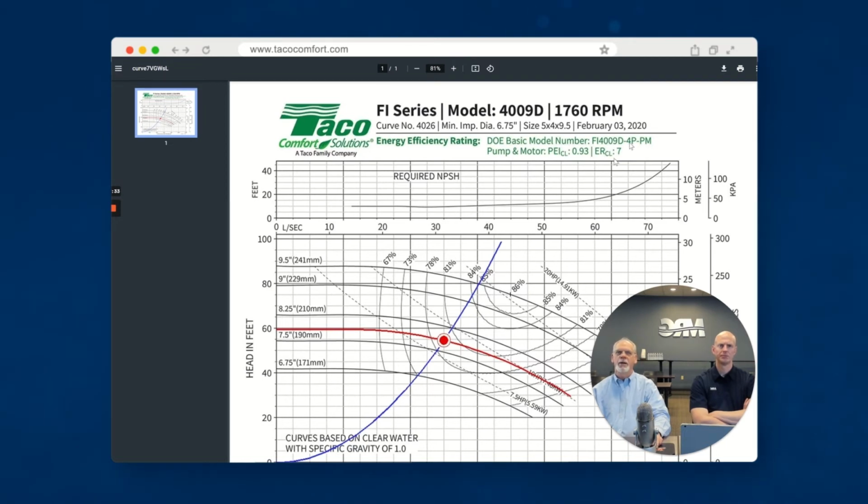This pump here does have a 5-inch suction. We can change again with a 6-inch by 5-inch suction diffuser to adapt to our system piping and help the contractor, so he's not having to make any changes in his piping sizes. We can make that change there at the pump.